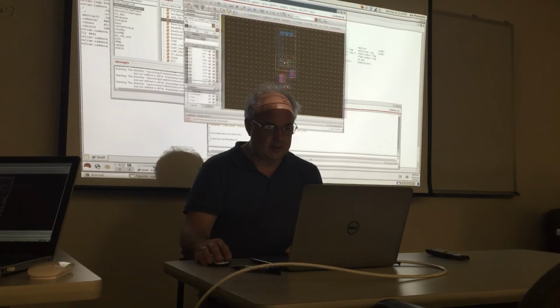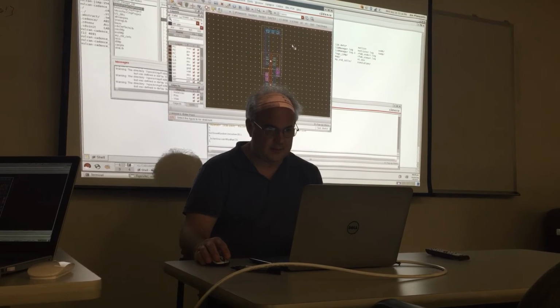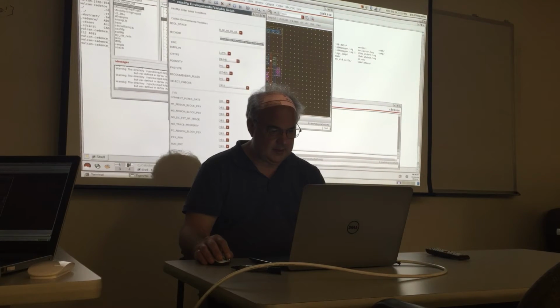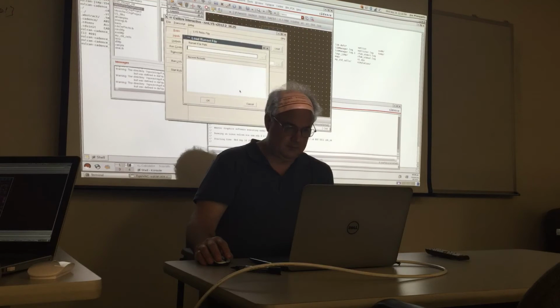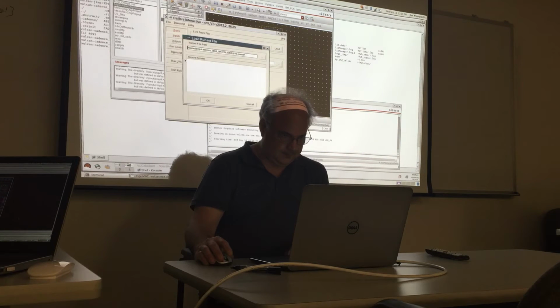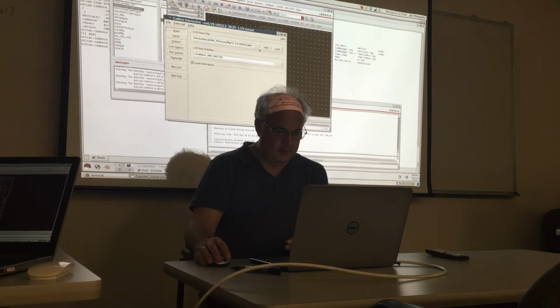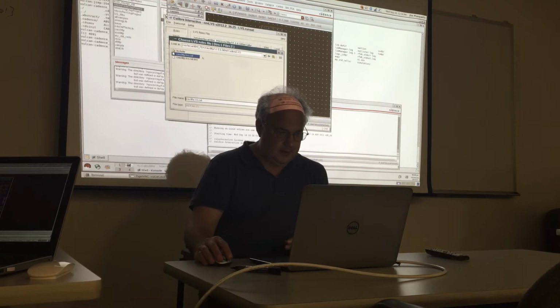Let me give you a quick look, because you guys are going to be using LVS to get these cells built. You'll go to Calibre, LVS, and then the same thing, hit OK. I actually have, like I said, run sets, and I keep them in Calibre's menu or subdirectory. One of the only things it does is populate the rules with the rules file, and the rules file is actually very similar. It's just the lvs.cal. You just go to the LVS directory.